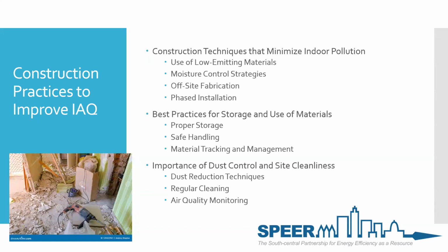And then the importance of dust control and site cleanliness. So dust control techniques: using tools to extract dust, wet cutting methods for tile and masonry, not just airborne all this stuff. I don't usually see that happening in construction for just high-end, high-volume homes. It's usually they're just dry cutting a lot of that stuff.